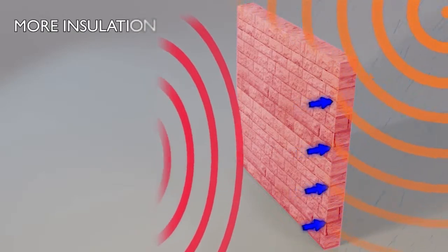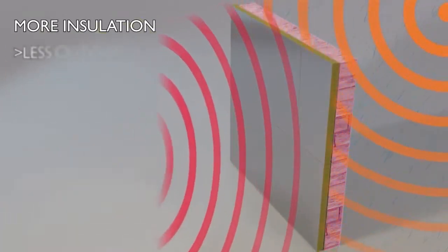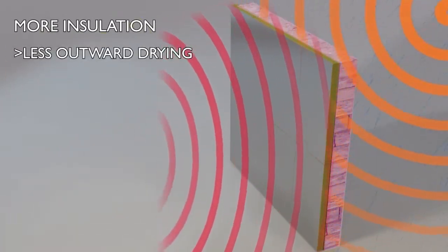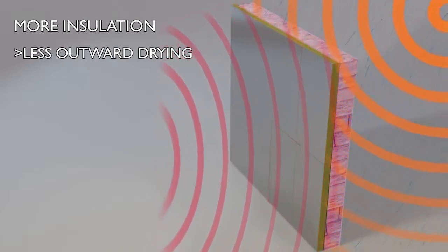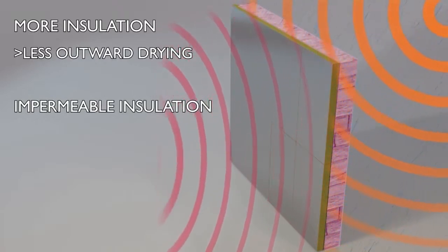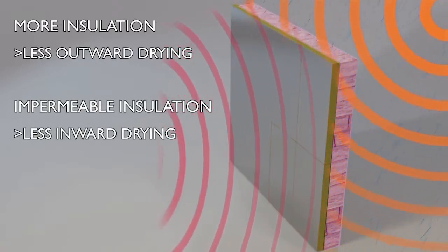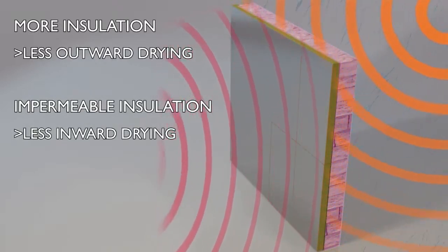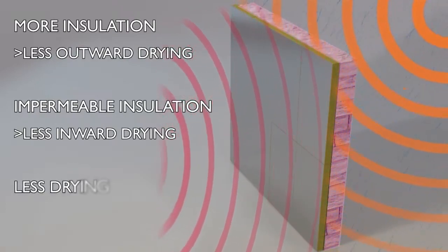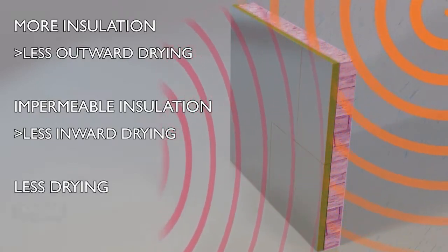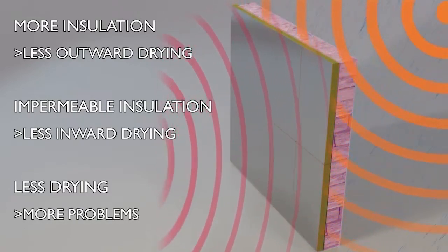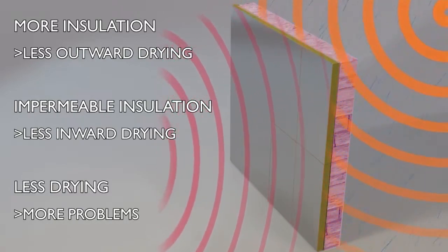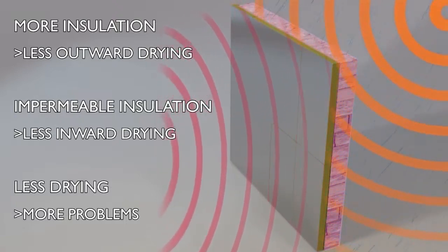If we add a large quantity of insulation internally, this can restrict the drying potential, driven by the internal heat source as the wall becomes colder. Furthermore, if the insulation is impermeable, as many high-performance rigid foams are, then the inward sun-driven drying can also be limited. If both these drying mechanisms are disrupted, the masonry cannot adequately release its stored moisture, leading inevitably to problems with damp. These problems may also be hidden behind the internal linings and not be immediately apparent.